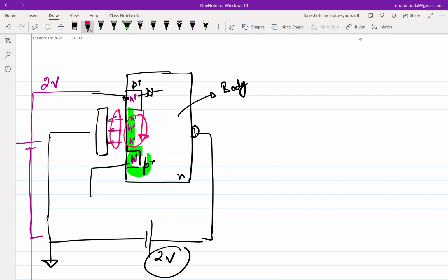You don't want the holes to be formed, just as you don't want the water to flow. You switch the tap off so that the pipe becomes thinner and thinner, which means you don't have any water flow. In this case, you don't want the mobile holes to be formed. In that case, all you have to do is ensure that this electric field goes off. How do you ensure the electric field goes off? Let's say I increase this voltage to 2 volt. Then naturally the electric field vanishes, because now this battery is essentially a 0 volt battery. You don't have any channel.